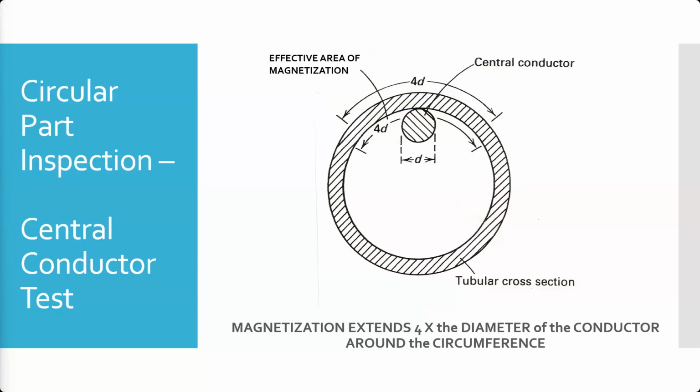Now, it's going to be really hard to turn a part 4.71 times exactly, right? So typically we round it up. No matter what, we're going to round it up. You don't round down. If it ends up being 4.4 and you round down, you're going to miss 0.4 of that part, right? So it's better to overlap slightly each time than risk missing a little piece of it. So 4.71, we would want to make 5 rotations or 5 segments.